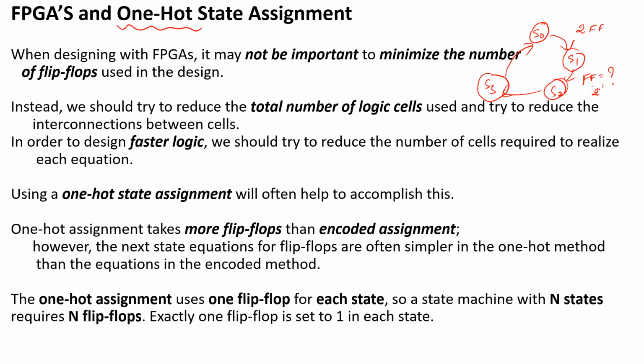So this is what we can understand about simple state assignment. For the state assignment, 2 flip-flops I'm using: 00, 01, 10, 11 is the state assignment that we have done. According to the state diagram, we can implement our circuit by generating the present state, next state and input, and the truth table, or we can say the state table.